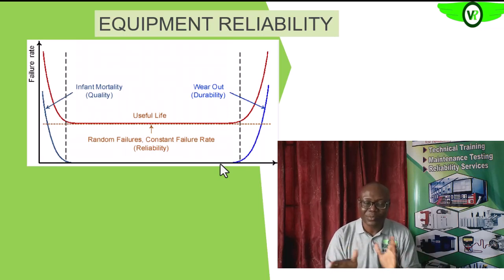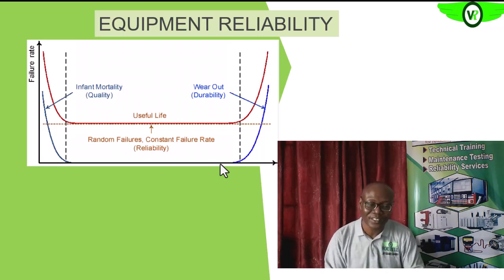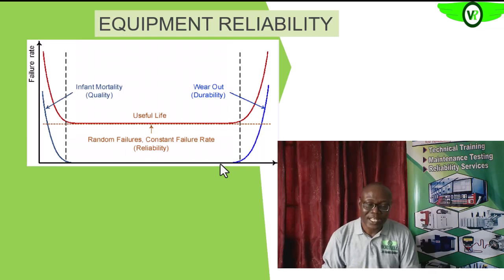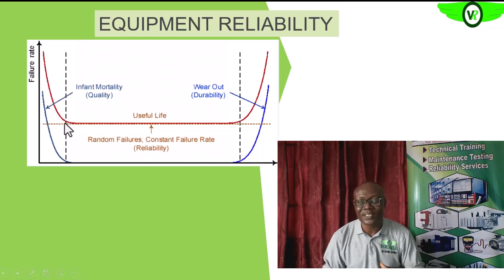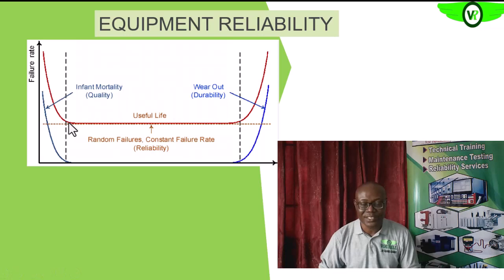These are some of the conditions. Then if it is an asset already in operation, things like an intrusive maintenance program can also cause maintenance-induced failure, increasing the infant mortality rate on our assets. Then if the asset survives this period, it has now bedded in, and it will enter the normal service life.